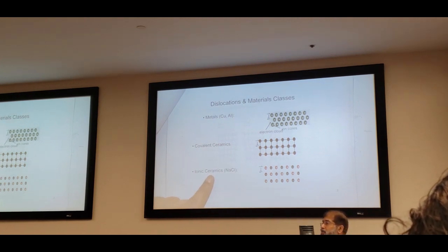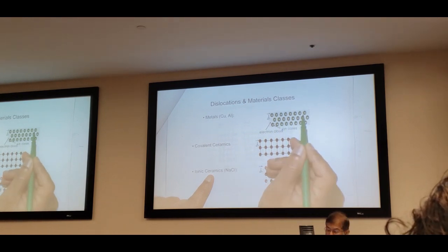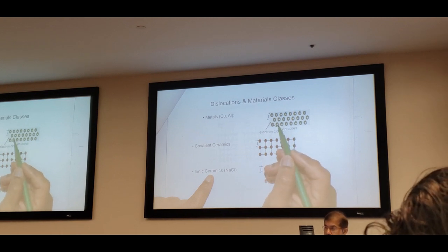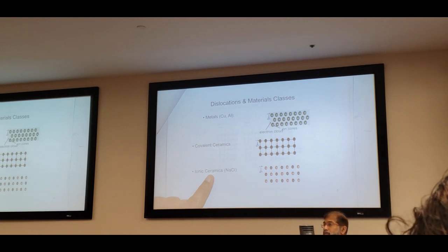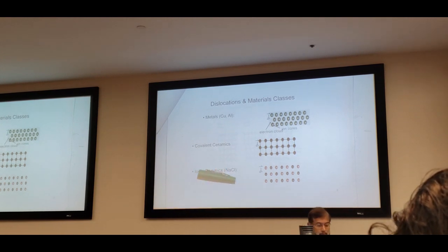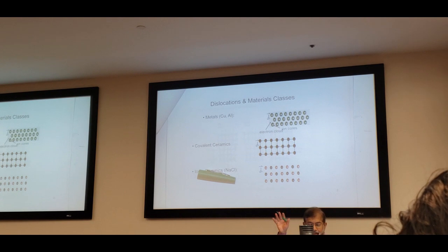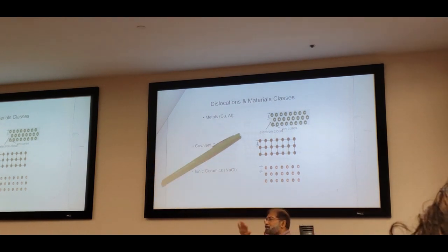And what is the characteristic of a metallic bond? Is it directional or non-directional? Non-directional. So now look at this one. Since the atoms are in a sea of electrons and the metallic bond is non-directional, is it easy to undergo slip? We are going to talk about slip later on, but I am just saying slip in general.